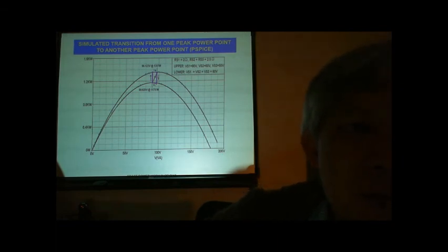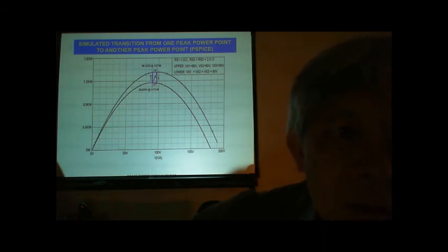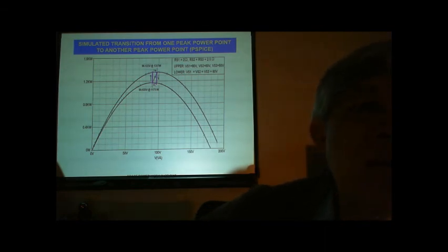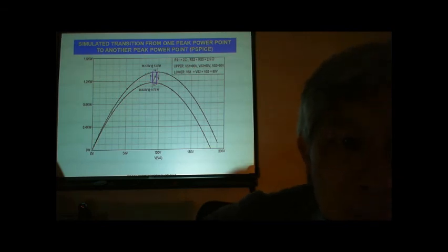This slide shows the simulation result providing the transition between lower peak power point of 1170 watts to the upper peak power point of 1357 watts as a result of the sourcing circumstance that changes from the identical sourcing voltage of three power sources on the lower curve to the different sourcing voltage of the upper curve, where source number 1 has 80 volts and source number 3 has a lower voltage drop to 50 volts while source number 2 remains the same at 60 volts.